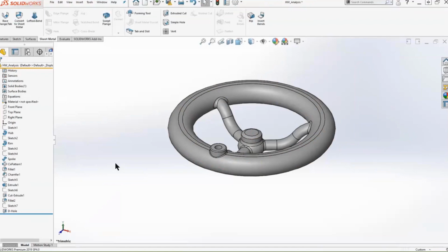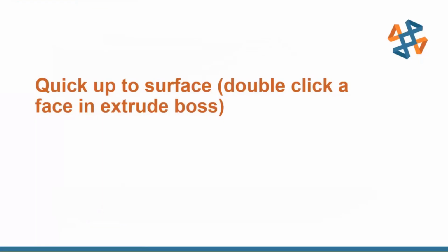So it's kind of one or the other. We've found in our testing, if you have a very complex model and you have many, many features, maybe hundreds of features, for example, in folders, you go flatten that out, you will notice a very significant lag when you try to select a feature, as behind the scenes, SOLIDWORKS is kind of unfoldering everything, to make some words up. You'll just notice a delay. So it's kind of a performance hit to have folders, large parts, and the flat tree. So kind of one or the other there.